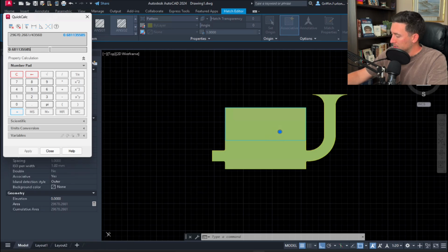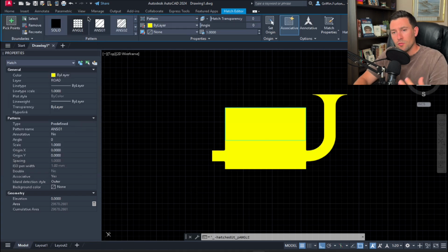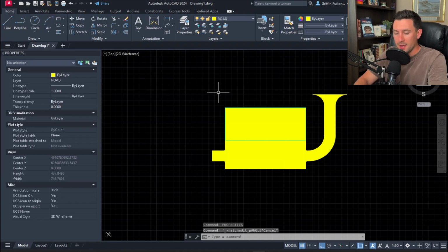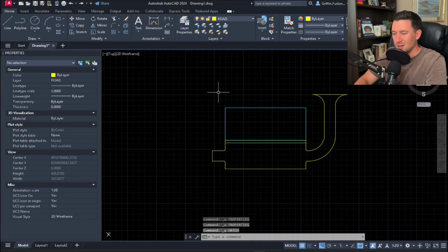And that's important because that's how much impervious area that we have. Impervious area, guys, means that water, when it hits any of these areas, it's not permeating into the ground. And this directly affects our CN value. Now, in order to just go all the way back, you can do Control Z. I'm just gonna do that.